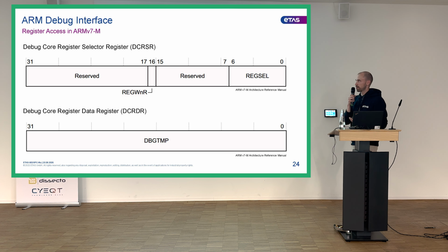And the nice thing about the system is that I can implement all of this myself. So if I take, let's say, some cheap debug hardware like an FTDI, like an Olimex or a FlySwatter, just some basic crappy stuff, then I can, just by doing these shift operations against the JTAG port, so just by shifting the instruction register and shifting the data register, implement all of this myself in Python.